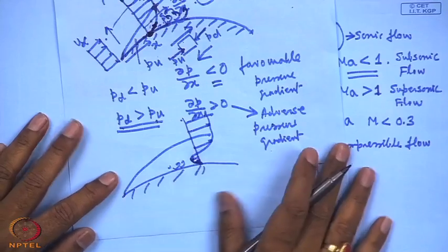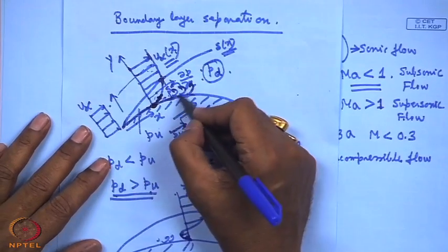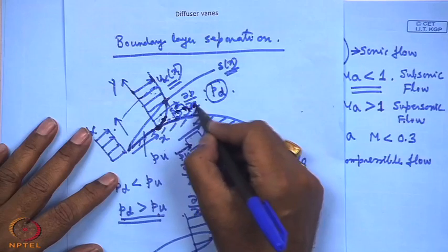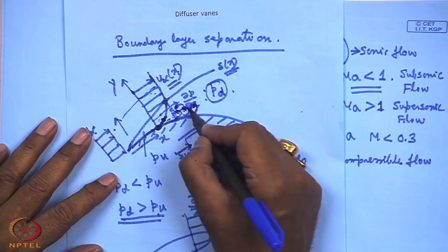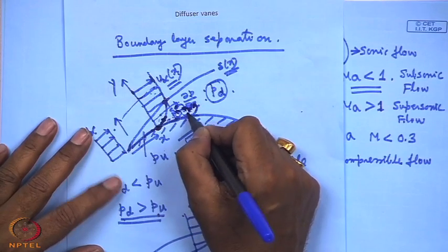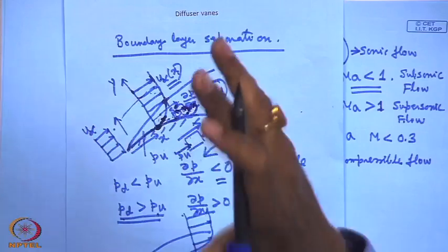This is known as boundary layer separation, and this creates a large number of eddies, recirculatory flows, by virtue of which the total mechanical energy of the fluid is being curtailed, is being reduced. Energy is totally conserved. Because of this creation of local recirculatory flow in the form of eddies, which takes place because of the flow reversals, the boundary layer is detached and all boundary layer assumptions fall there.